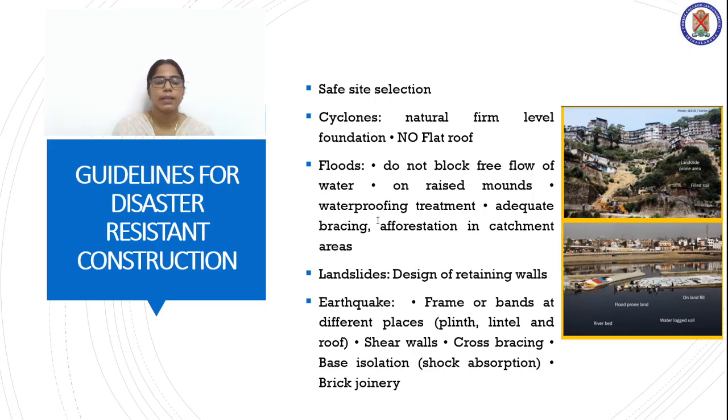And restricting the width of the openings, using bond beams, and taking recourse to steel or wooden dowels as well as RCC bands at plinth, lintel and roof levels are good disaster resistant techniques for buildings in the case of earthquakes. In the case of cyclones,